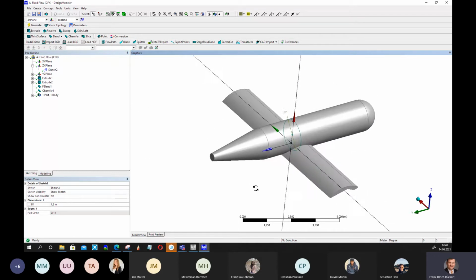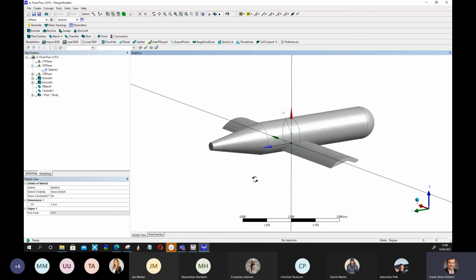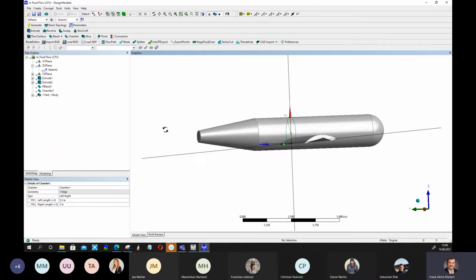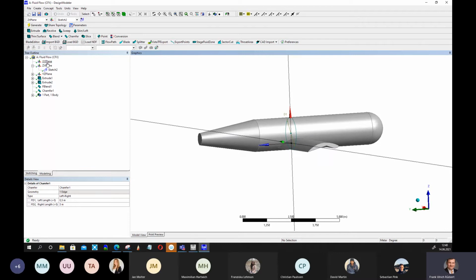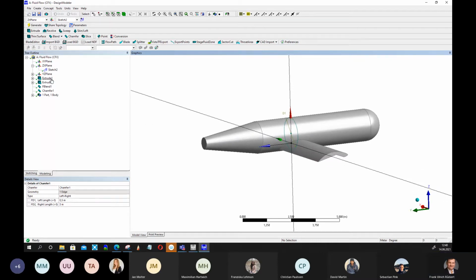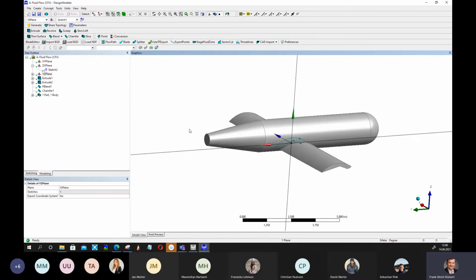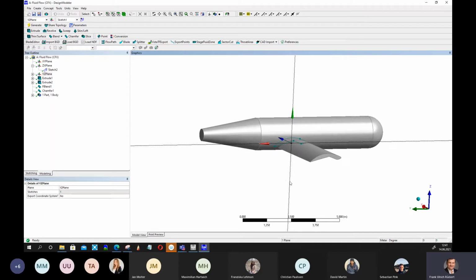I need additional wings here at the tail. And to do it, I choose the chamfer, maybe it's a bit smaller here. Right. Generate. And I add some additional wings here on the ZY plane. And now I don't want to mix it up with my main wing.